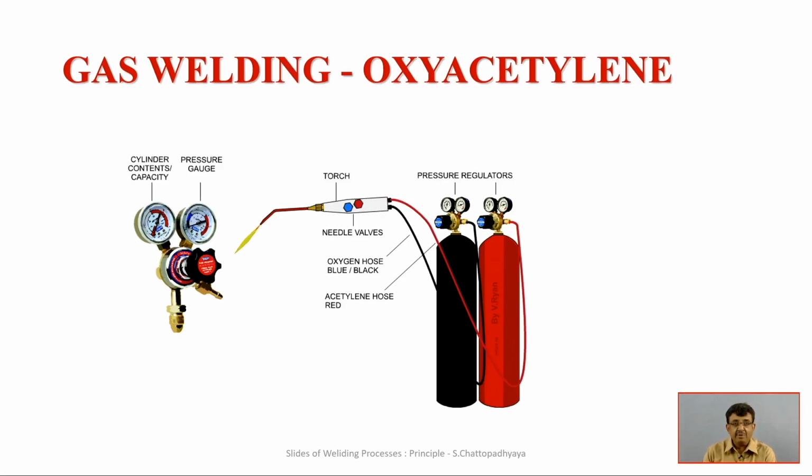And the valve closing also differs, one is clockwise and the other is anti-clockwise, in order to ensure which kind of cylinder it is. In remote inaccessible areas there is always a chance that the paint on those cylinders is eroded, so the color will not be visible. Even in terms of the locking arrangement of those valves, one can easily point out whether it is an oxygen cylinder or an acetylene cylinder.